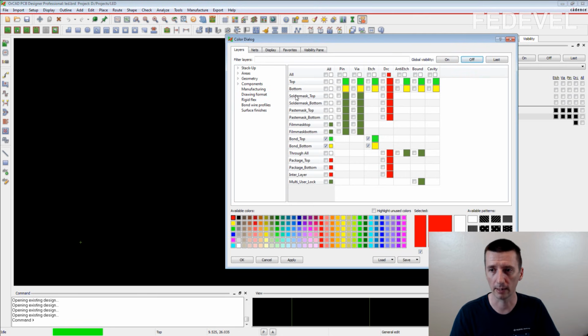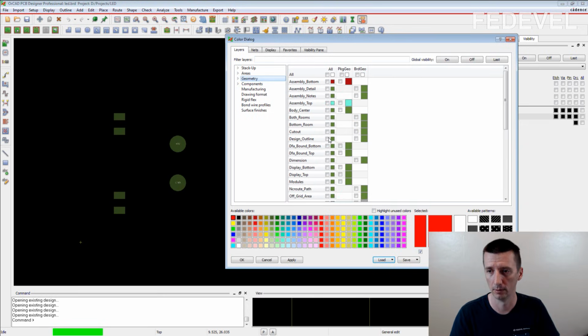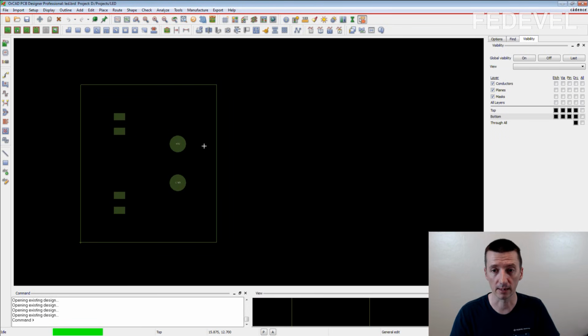Now I'm going to create the solder mask top layer. This is the layer which specifies where the green color is going to be on your board, and it is a negative layer. So all the empty space is going to be the green color, and this, which you can see here, there is no green color. So there is no green color on the pads of the components.